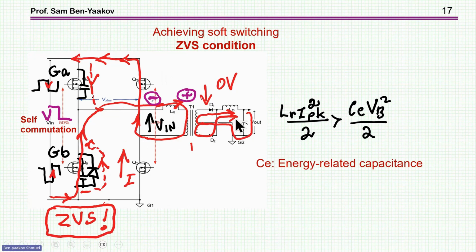That is, it has to do with the output power, because we sort of froze this current at a given point. So this is nothing we can control. It has to do with the power level of the system. What is taken into account in the design is how much inductance I need. Now, if the inductance is too small, then this process will not be completed and will be stuck at the midpoint. I'll show you a simulation in the next slide.